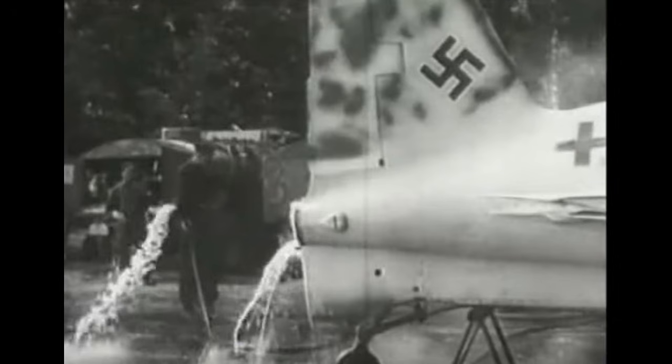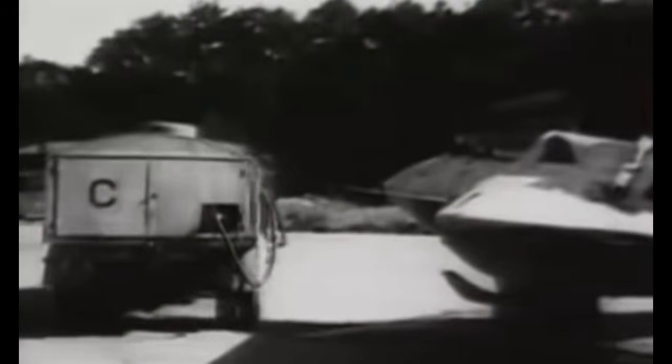First, the entire plane has to be washed down by running water on it and through most of it. Notice in this picture, water is actually coming out the tailpipe. Everything fuel touched was purged with water: tank, lines, rocket engine, everything. After that, that's probably the point where the armorers serviced the guns, although I don't have a source for that. Next, the C-Stoff crew comes over in their C-Stoff truck. The C-Stoff crew handles only C-Stoff, nothing else.